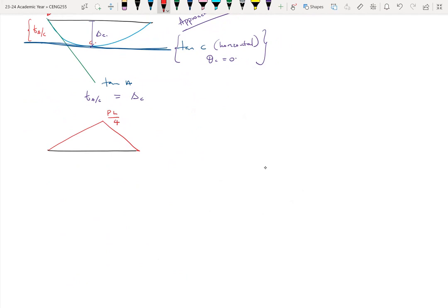Okay. So there's a bending moment diagram. If you want our M over EI diagram, we just divide that, assuming that in this case, our M and EI are constant. So our plot remains the same, but now it becomes PL over 4EI. So this becomes our M over EI diagram. They look about the same, but they are actually different in the sense that in one we are dividing the moment by the flexural rigidity.